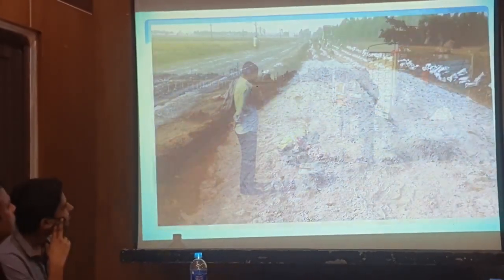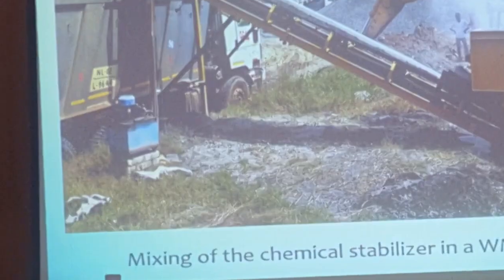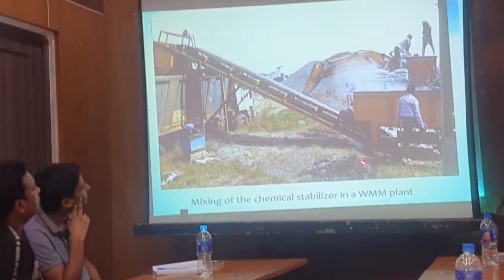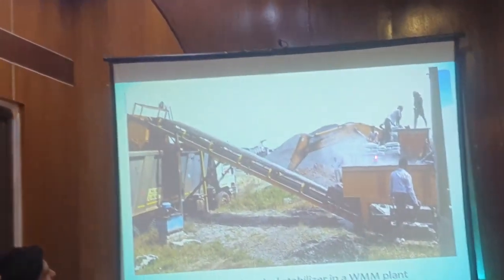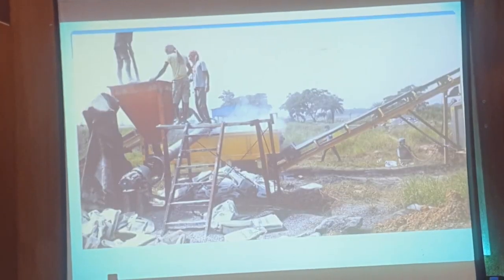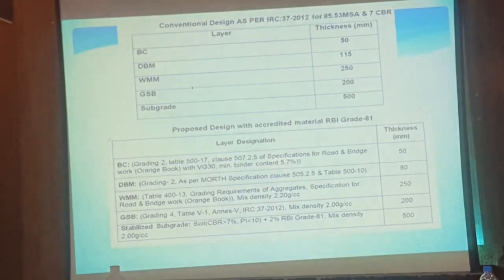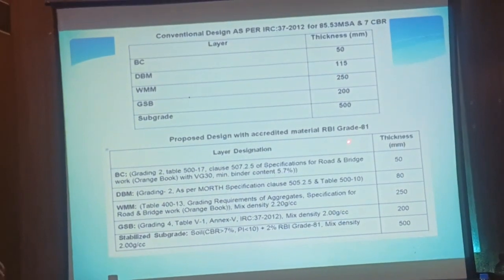It's being done like that. The subgrade has been done and is being tested. And in the WMM layer also, this stabilizer has been used, these are the bags. It is mixed in the WMM plant, and the WMM surface is laid. And this is the advantage of this one.